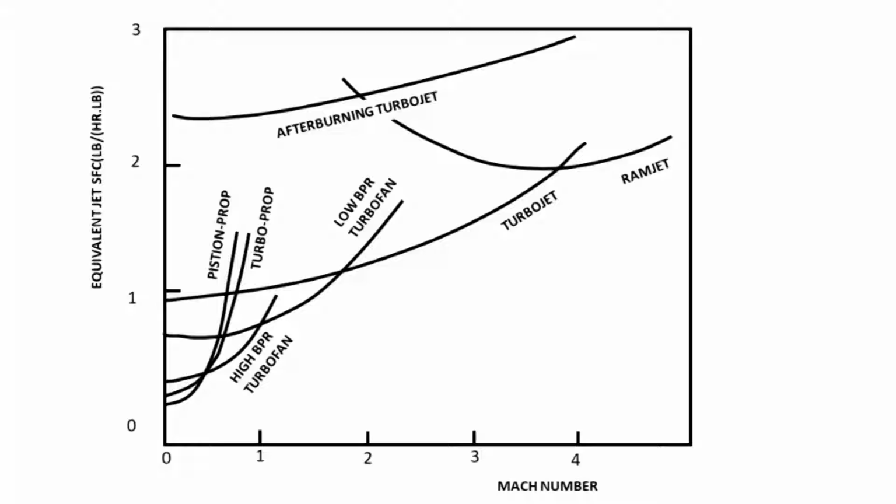You can refer to the figure there, and for different combinations of engine, different types of airplane, and the Mach number you are flying, you can pick the value of CT based on historical data. But I repeat again, these are all initial preliminary sizing. So these are some guideline numbers. Finally, anyway, we have to modify this, improve this, right?